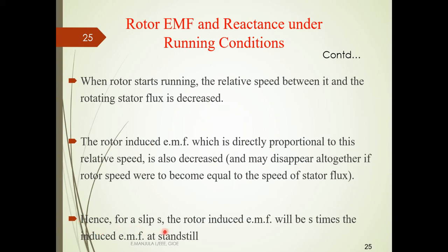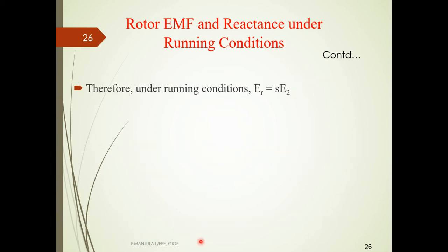Hence, for a slip S, the rotor induced EMF will be S times the induced EMF at standstill. Therefore, under running conditions, the rotor EMF is equal to S times the standstill rotor EMF.